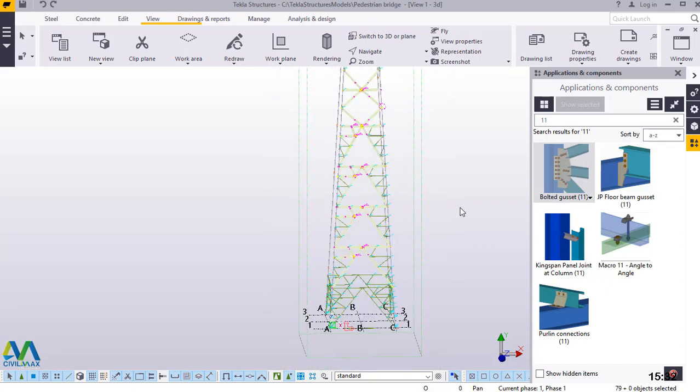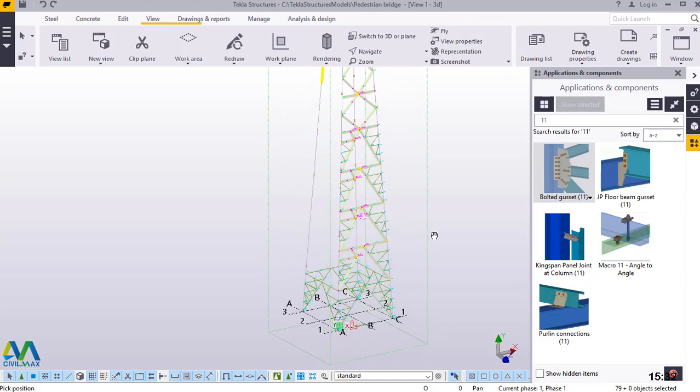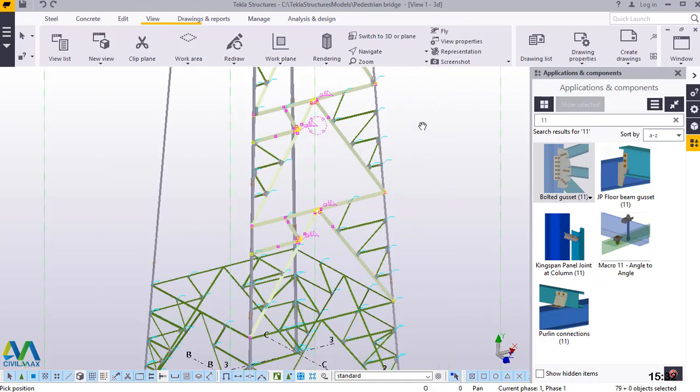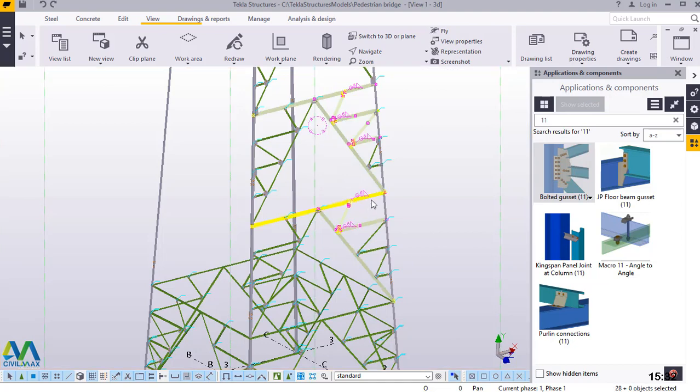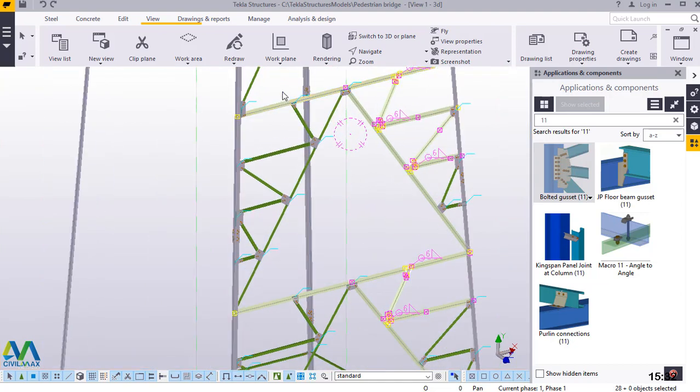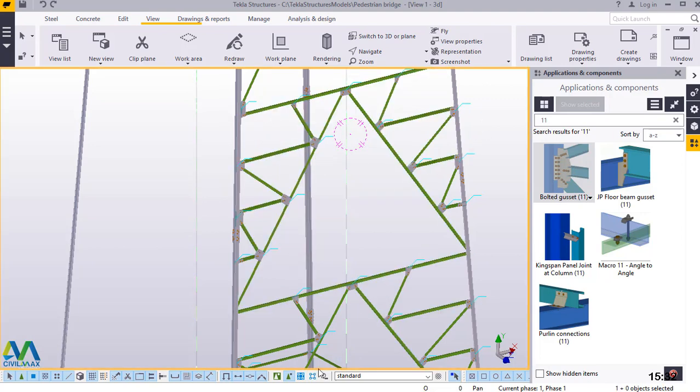Once we've done that, we'll make sure everything that we intend to mirror on the other end has been picked properly. Let me just undo that. First of all, let me select everything there. I'll press Control, zoom out and select everything here. Pick on that, pick on this, and I'll make sure first of all that my assembly is active.